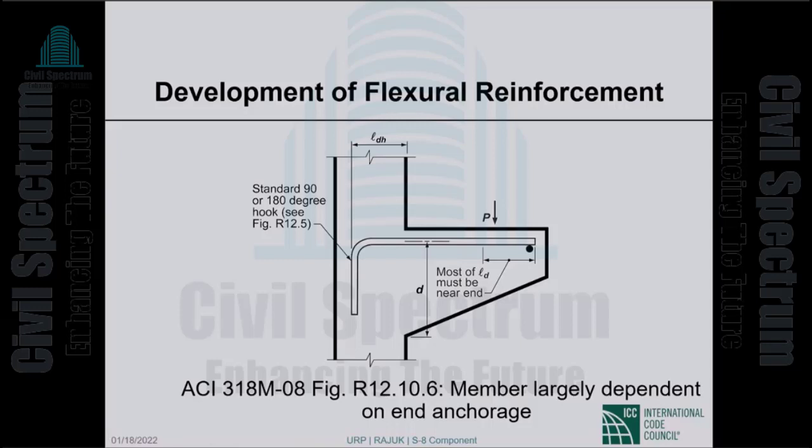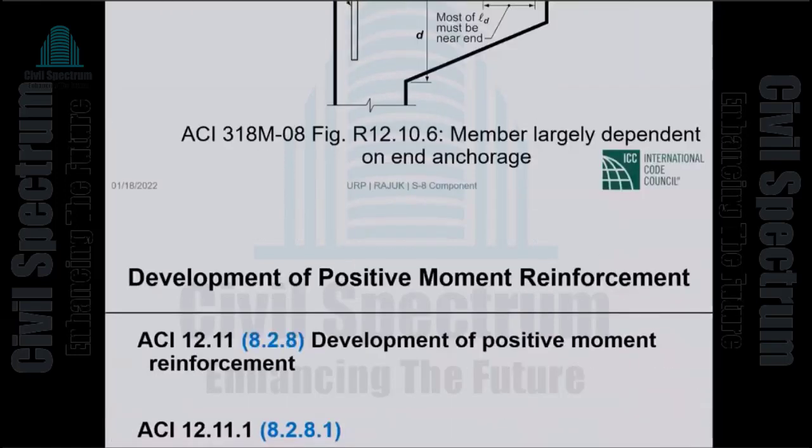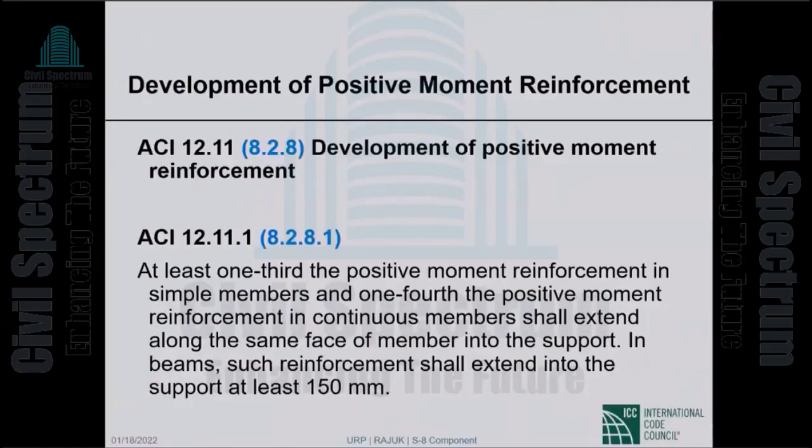How do you develop it? And the suggestion, most people would weld a rebar typically of the same diameter as shown in the picture, and that welded bar will provide the anchorage. So this figure is also in the commentary to ACI 318-08. There is some language to go with the figure, and I would recommend that you get hold of it and read it.